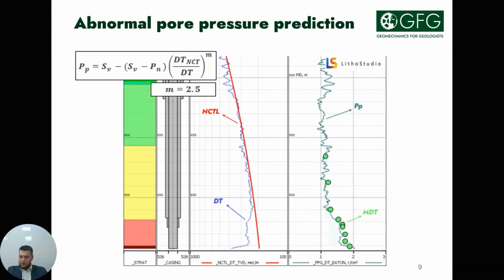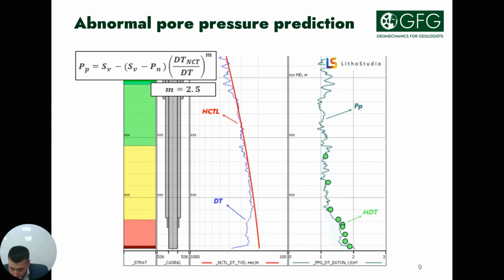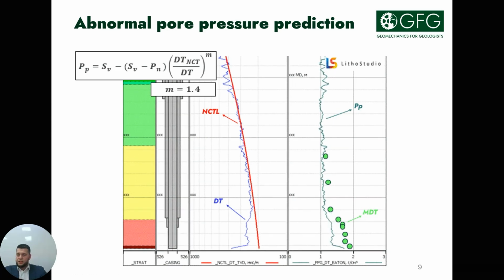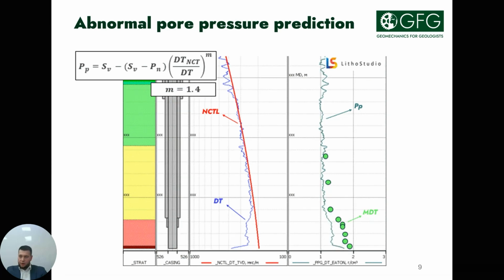So let's start analyzing the main problems that geomechanics solves. The first problem is to predict abnormal pore pressure. This is very important when drilling deep wells, especially exploration wells. It can cause serious drilling events, in particular fluid showings, increased gas readings, emissions, and so on.